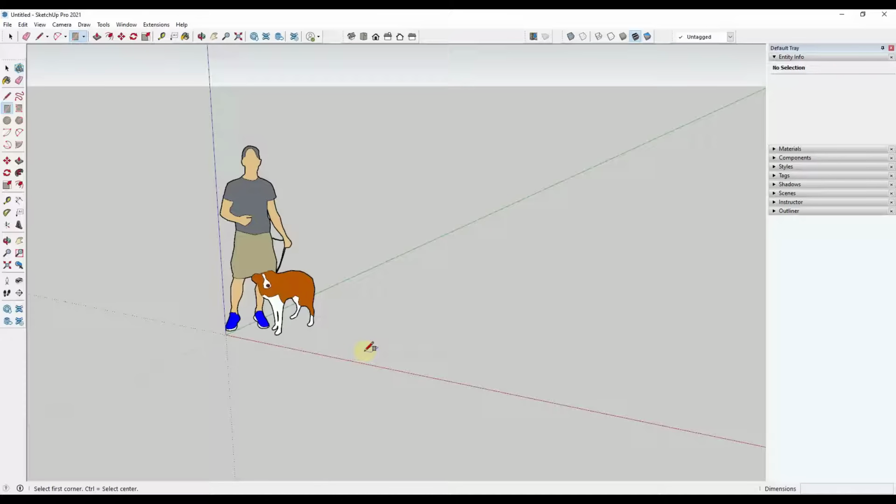And so the first thing we want to do is single click in order to set a base point. One thing to notice about this is I am not clicking and dragging. What I'm doing is I'm single clicking and then moving my mouse. Well, what that does is that activates this tool. And if you look in the lower right hand corner, you can see how the dimensions in there are live. And what that means is that I can actually type in values for my box.